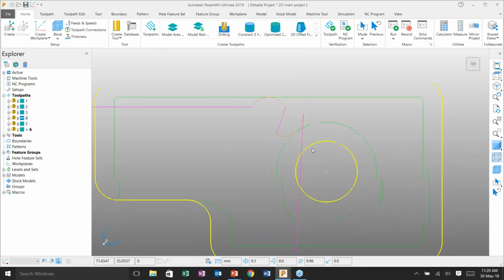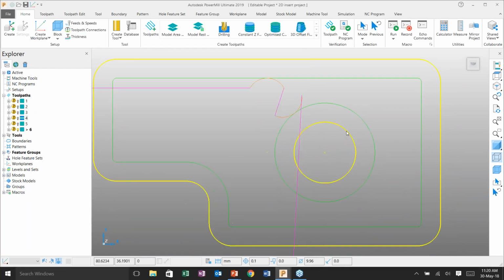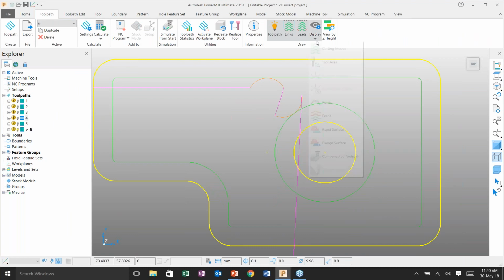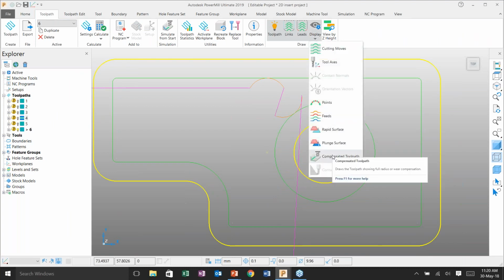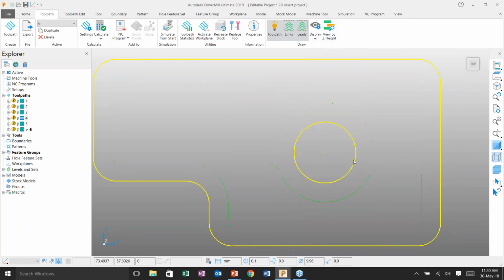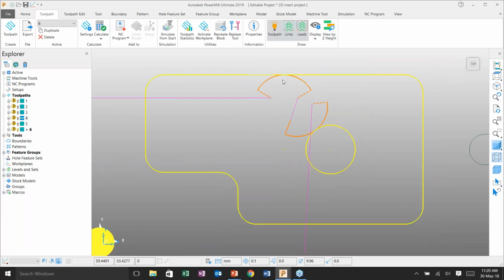To make sure your 2D cutter compensation is active, you just go into your toolpath page, come under display, you can see a compensated path, you can draw it, you can see that it is fine. You can start from 0.1 diameter. The tool I had used is 10 mm, so you can play around with the tools while doing your machining.